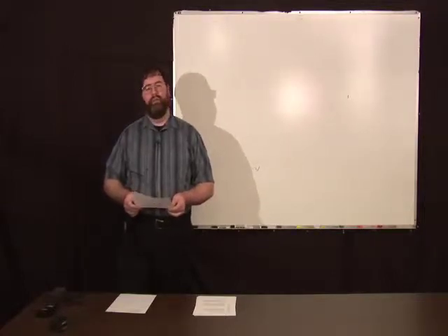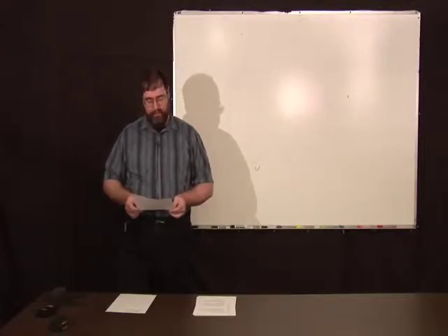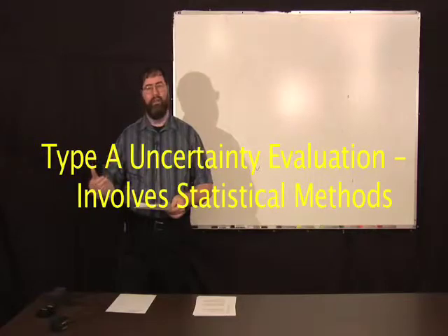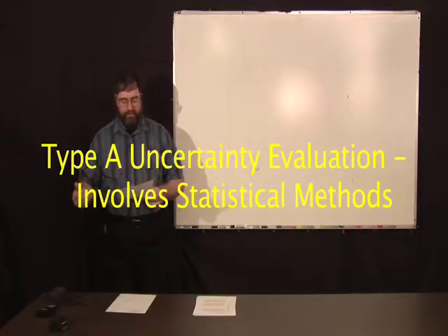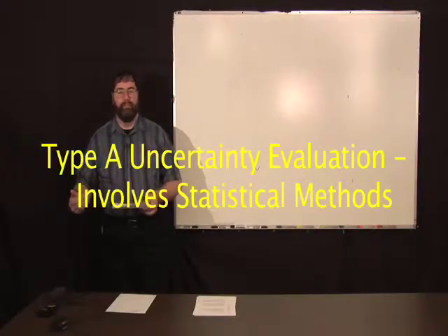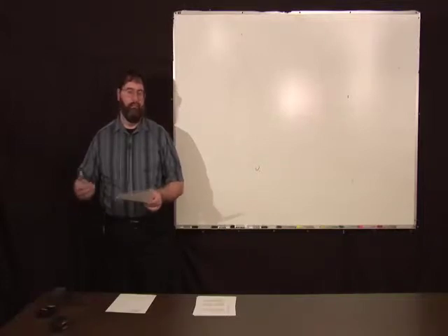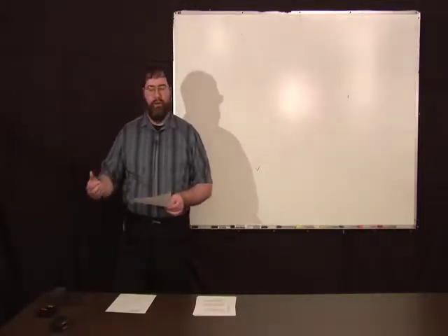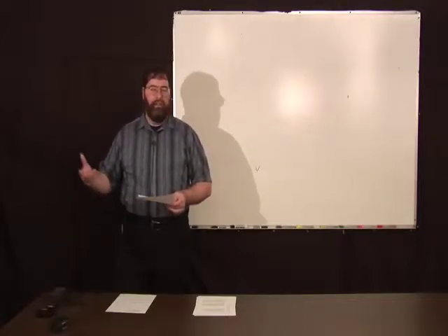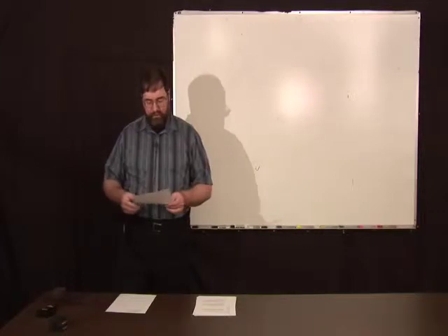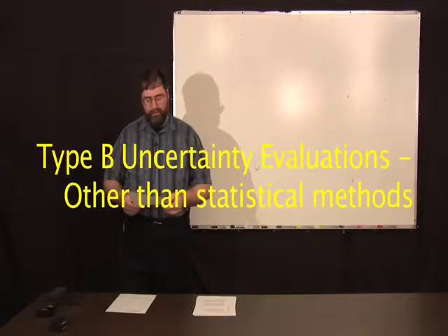And the ISO breaks uncertainties into two categories. You have Type A evaluations of uncertainty, which is a method of evaluation of uncertainty by the statistical analysis of a series of observations. Something like standard deviation or variance would be measures. In some cases it might be something like Allan variance or something else, some statistical measure of a series of observations. Type B evaluations of uncertainty: